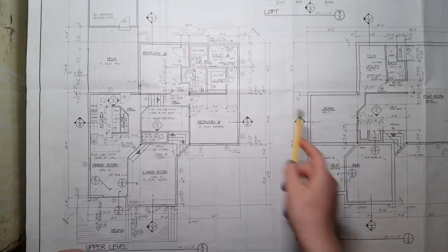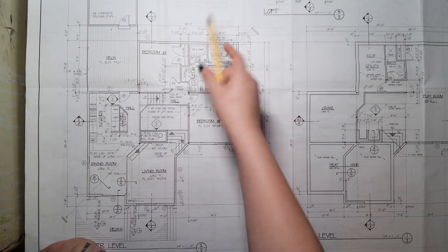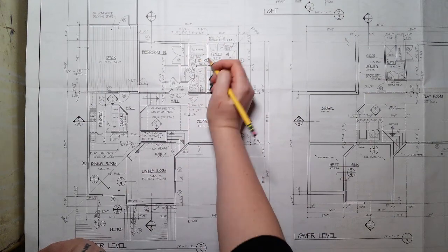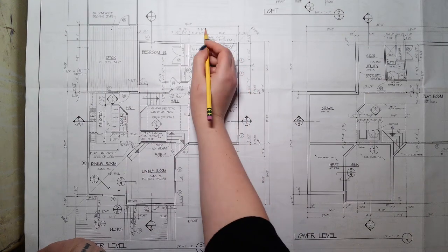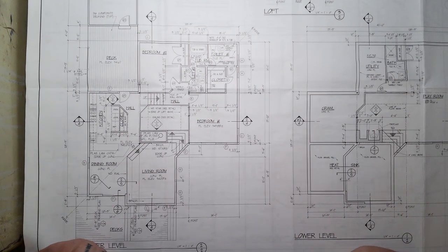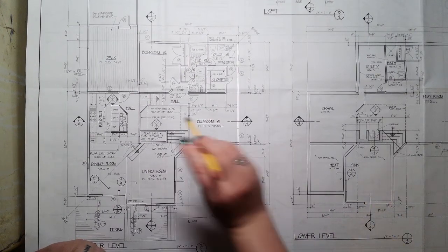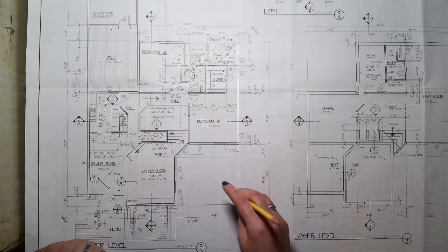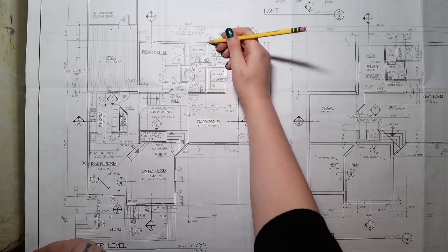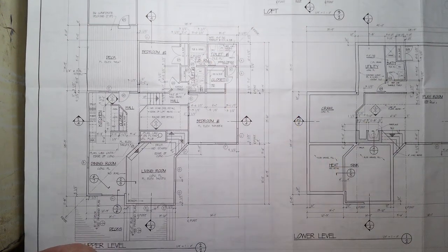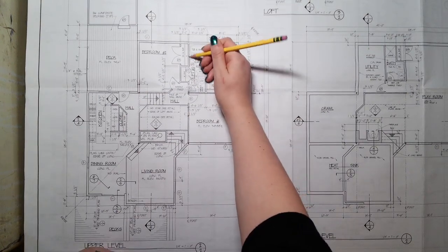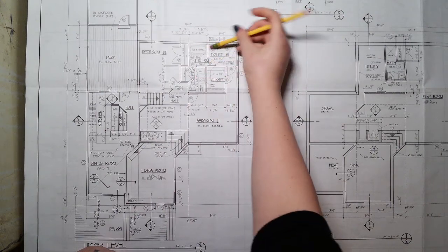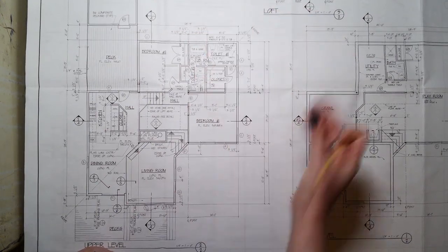What they have instead is from the outside of the wall to the edge of the wall to the edge of the wall. And I can see that these walls are framed out with 2x4s, because they're saying that the wall is 3.5 inches wide. In these plans, they didn't even specify gypsum wallboard on either side or any of the framing materials. They've only laid everything out based on just the framing structure. So this room is going to be one square inch smaller based on the gypsum wallboard, but it's really not going to have too great of an effect.